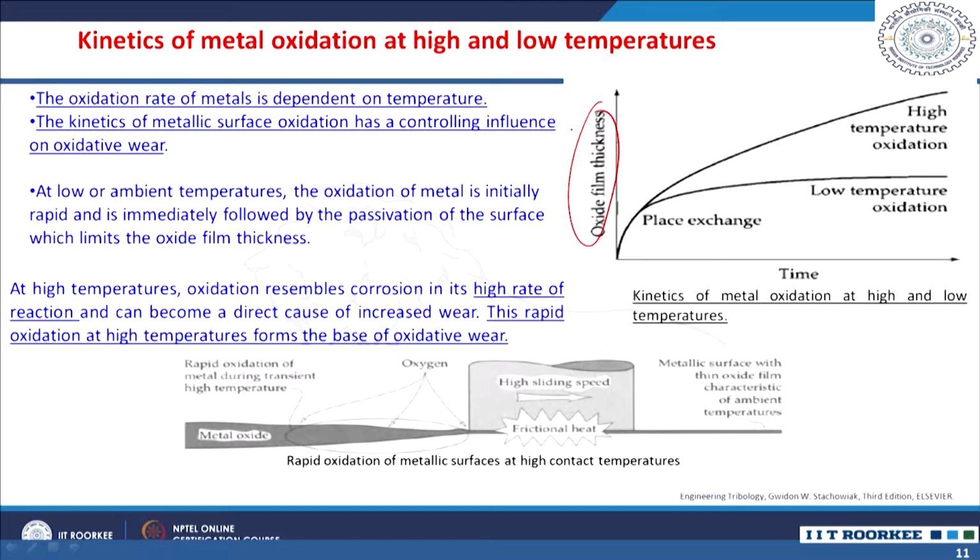So, you can see the oxide film versus the time. Initially there is a low temperature oxidation and then the high temperature oxidation. You will have lesser film thickness in lower temperature oxidation. But at high temperature, oxidation resembles almost corrosion in its high rate of reaction and becomes a direct cause of increased wear. So, you can have an oxide film thickness also increasing to a larger extent.